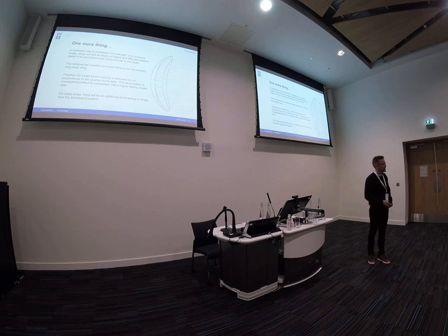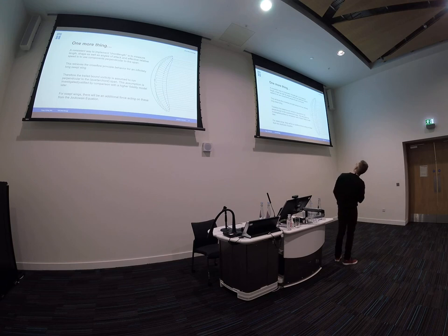So this is a free choice that I've made, and I made that because of the cross-flow principle. You can't make a very long, like infinitely long 2D wing, and if you turn that, you can't get anything right until you realize that you have to use the direction perpendicular to the span. So that's why I do this, and I'll impose this in my solution and see how it works. But if I put it like this, then this vorticity that goes in this bound direction here will have a force on it, because now it's not aligned with the main flow direction. So I need to include that part of the force in my solution.